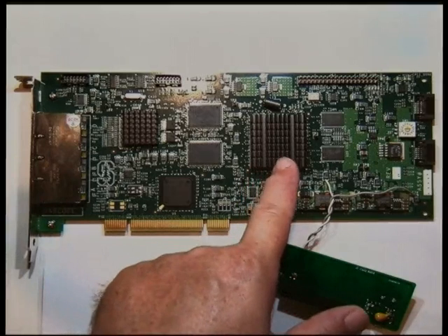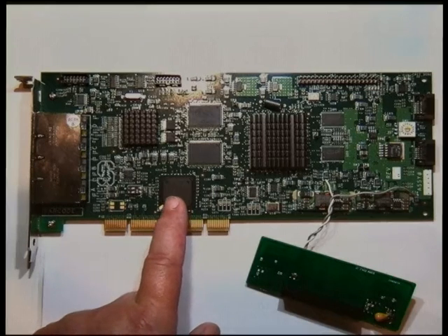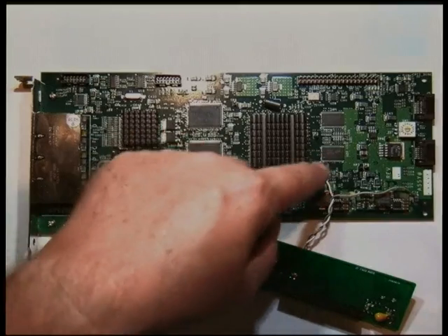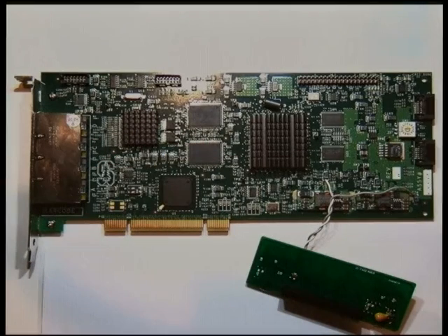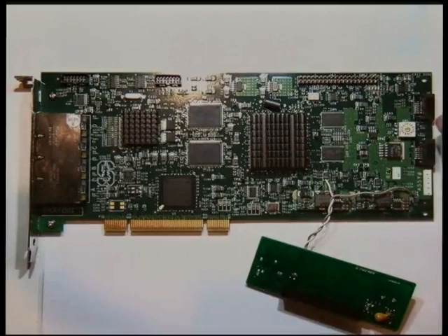The Virtex-2 Pro FPGA is underneath there. There's another FPGA just here, which is used for the PCI interface, also a Xilinx device, and there's a Broadcom four-channel GigE transceiver chip. There's also some RAM, some dynamic RAM and some quasi-static RAM. There are 2 SATA ports over there.